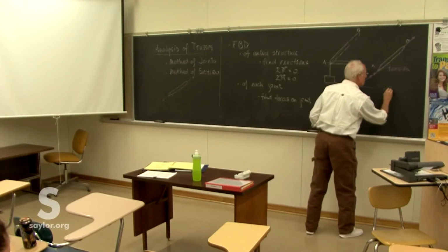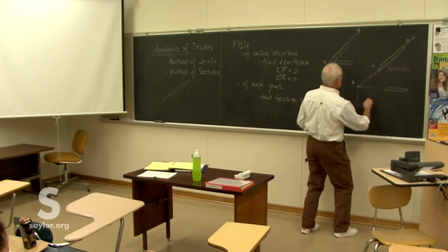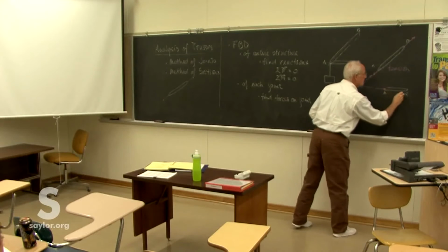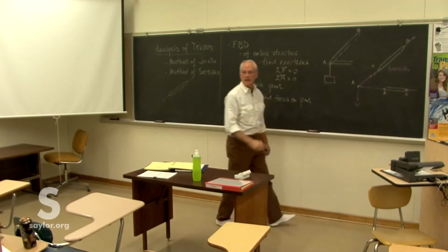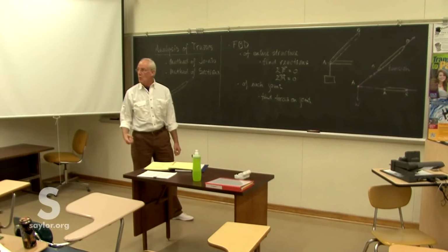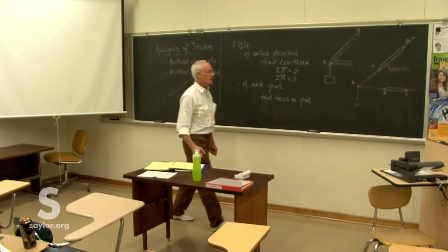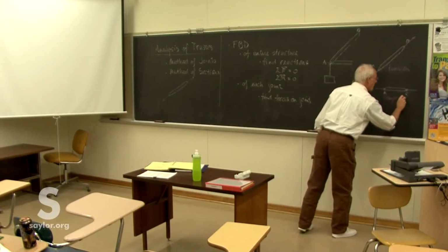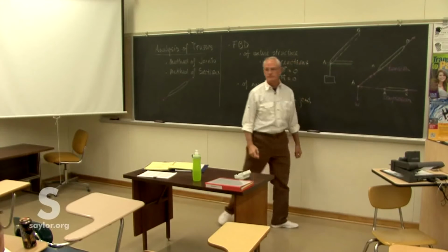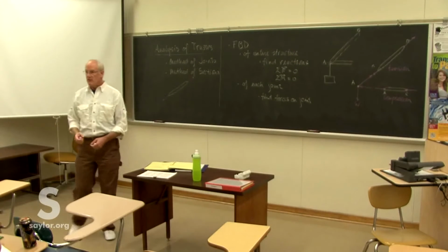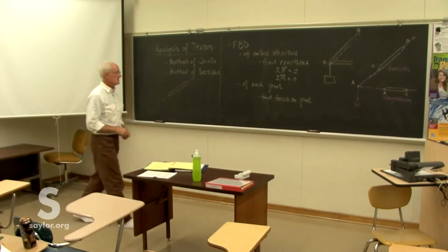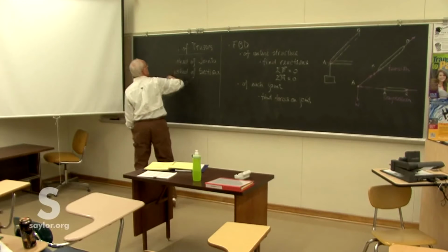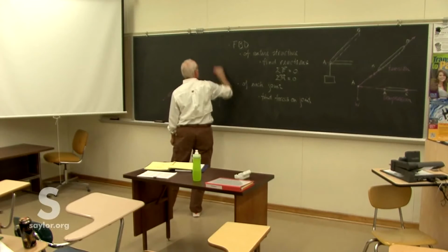The other member, I think I call that AC, must have forces like that, and it's in compression. We need to know that because that's part of the design of each of the members when we get to that. You can do very different things designing a member that's in tension and other things to one that's in compression.